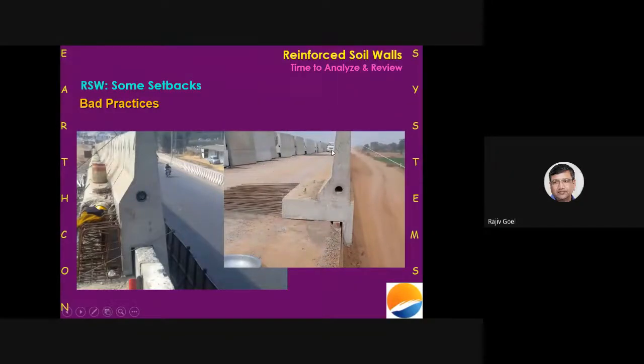And we all understand that in case the crash barrier is not stable, we do put a wooden block and people come up and say, this is only a wood which will go away or will disintegrate at some point of time. But eventually, this is all transferring the load to the fascia panels, which has to be avoided. And how we can avoid it, I'll come back to you in a little while.